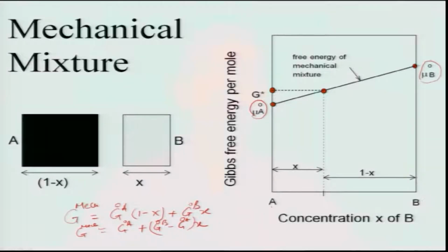Solution, what is the meaning of solution? Solution is very simple. If I take water, add salt and sugar, and stir it nicely for about 2-3 minutes, it will be a solution. And if I add more sugar, there is a limit of saturation, beyond which sugar will not mix in water. This we all know from school physics, there is no need to explain it. The same thing can be translated to solids. In solids, the same situation can happen. I can add carbon into iron, I can add manganese into iron and make a solution.